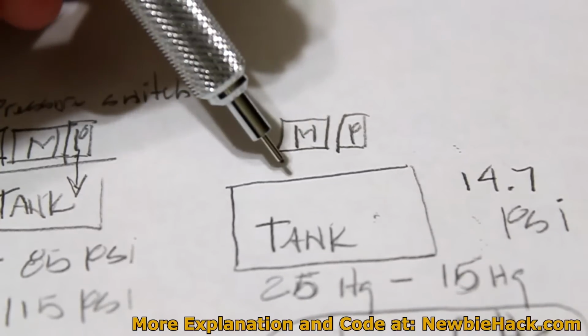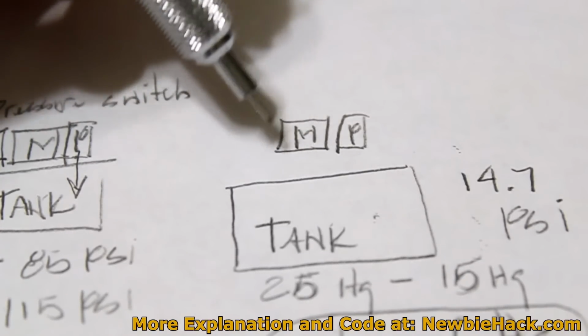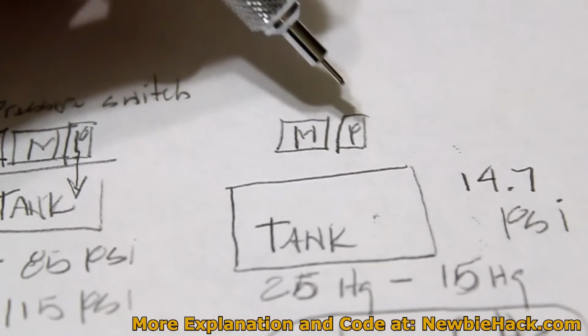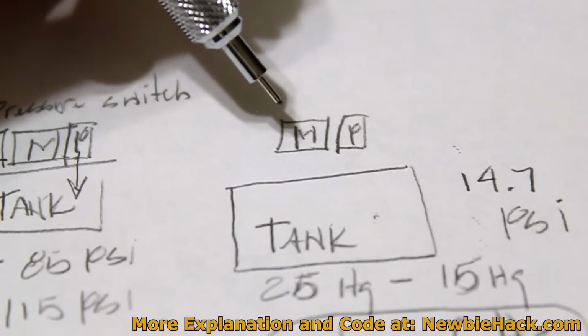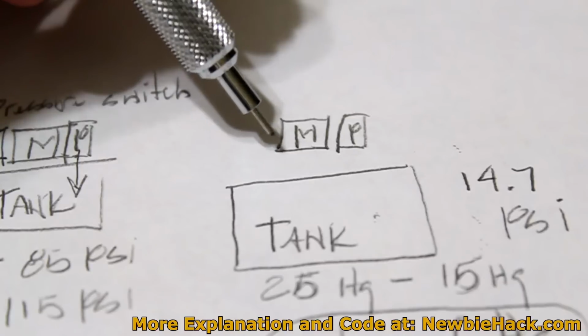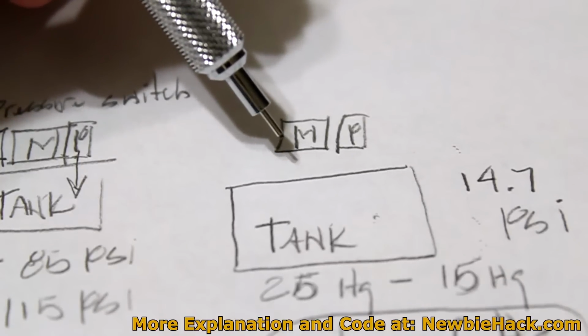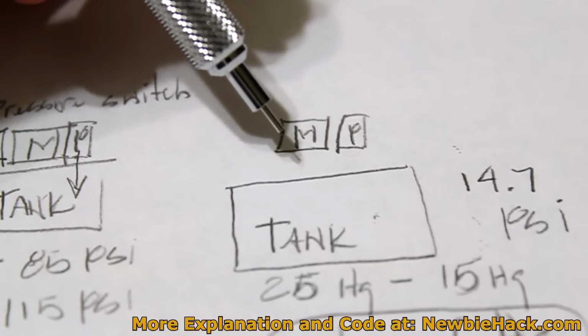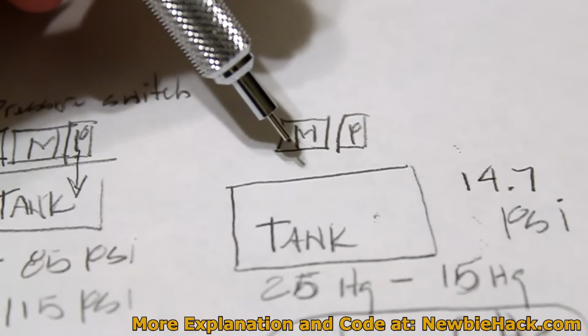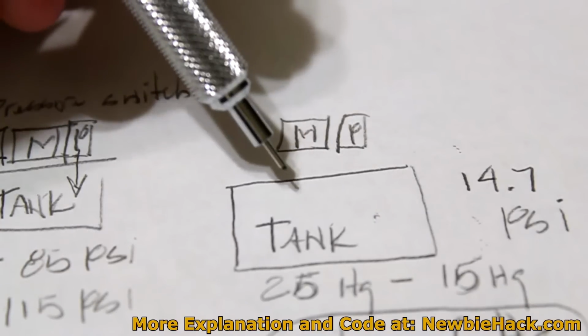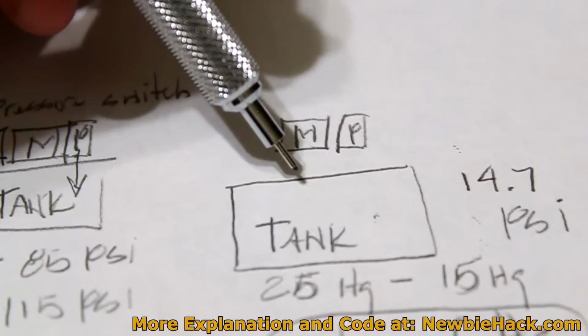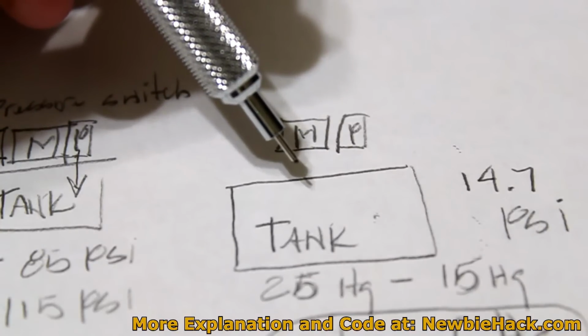So using this method, we'll be able to save some electricity with the motor, and also because my vacuum pump is relatively loud, probably around 60 decibels. I'd rather not have that ambient noise during the use of the pick and place machine. I'd rather have relative quiet around that machine most of the time.